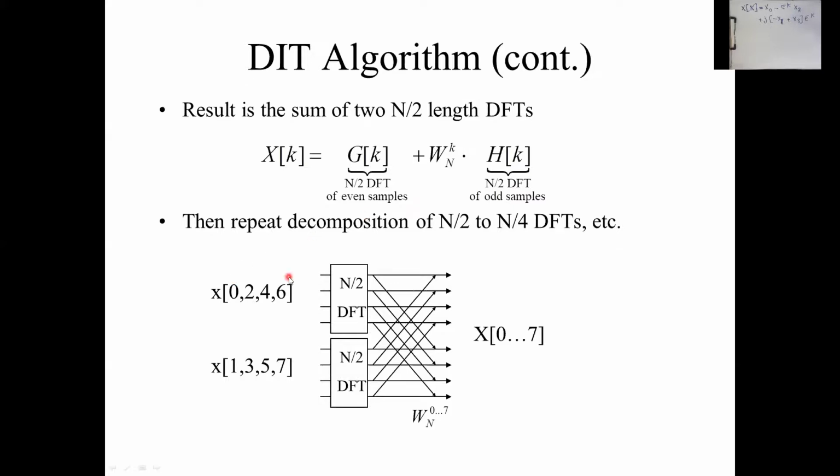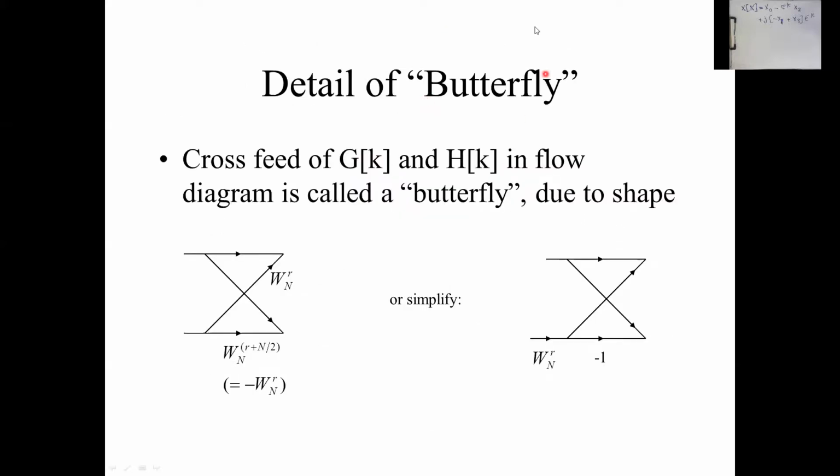The fast Fourier transform is an enhanced, simplified algorithm where you can perform the DFT by separating the even terms and the odd terms, and then performing the DFT separately for the even stream and the odd stream using what we will call the butterfly model.